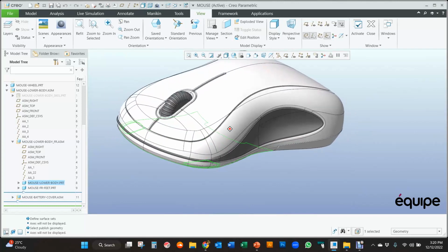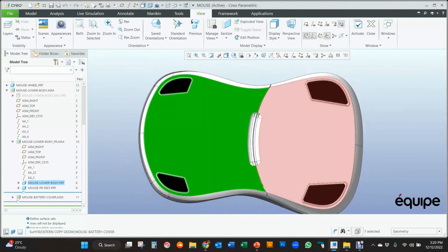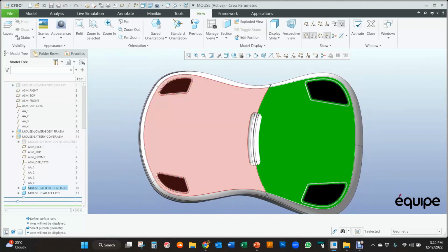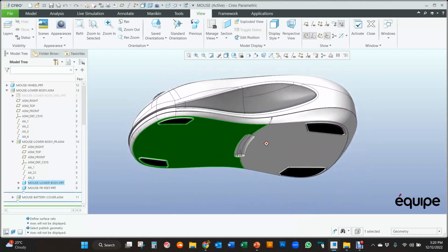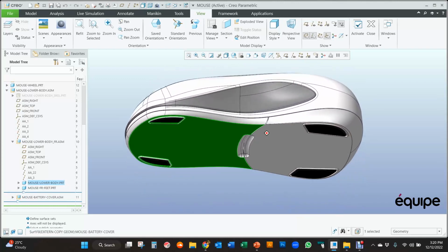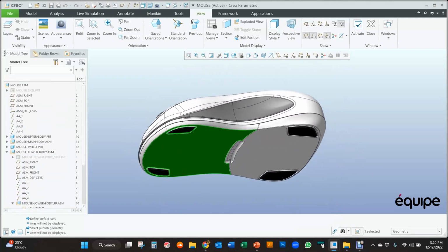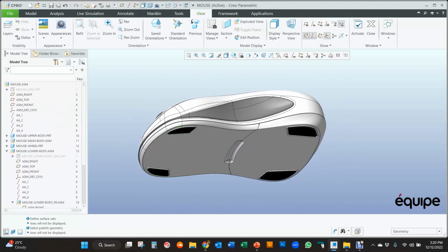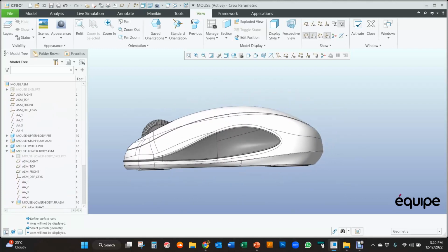That can give us some very nasty failures with circular references, where if this part falls over, the features in this part will fall over because they're relating on that parent-child relationship from that other part. You won't ever get circular references when you're using top-down design if you follow nice disciplined practices and only take references from the top level. If your top level skeleton falls over, then everything else will have errors, but it's only in that case.